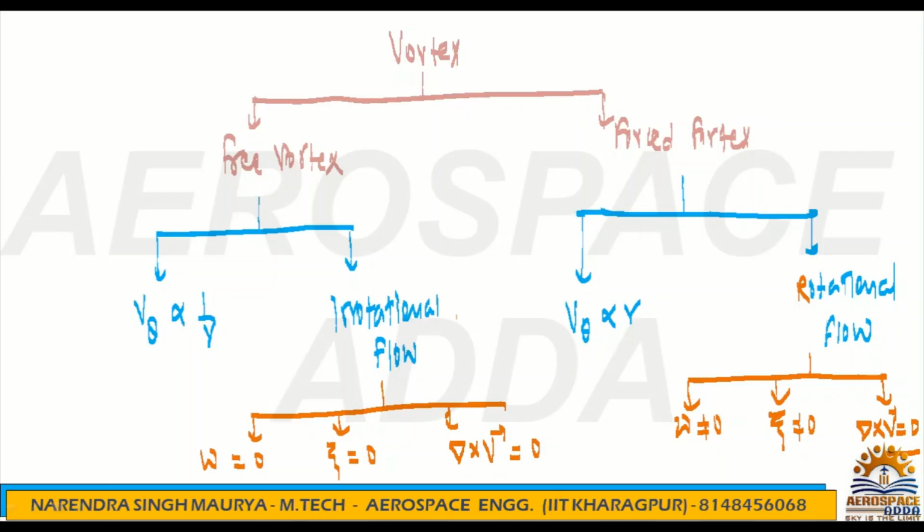Okay, so also the viscosity is the main reason for the rotation. I will also discuss sometimes when it comes. But meanwhile, here you have to remember, if it is free vortex, it will be considered as irrotational flow. If it is irrotational flow, then it becomes ideal flow, approaching towards ideal flow or potential flow. So that time you are free to apply Bernoulli equation. So here, in case of the free vortex, Bernoulli principle or Bernoulli equation works here.